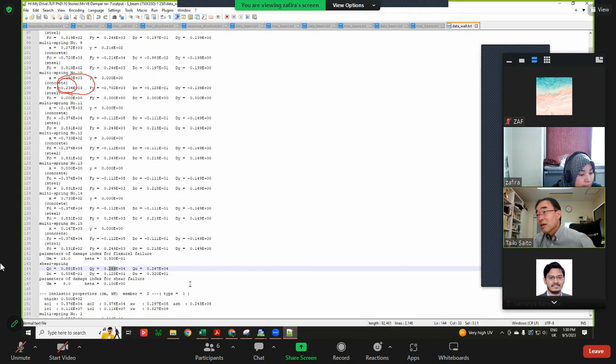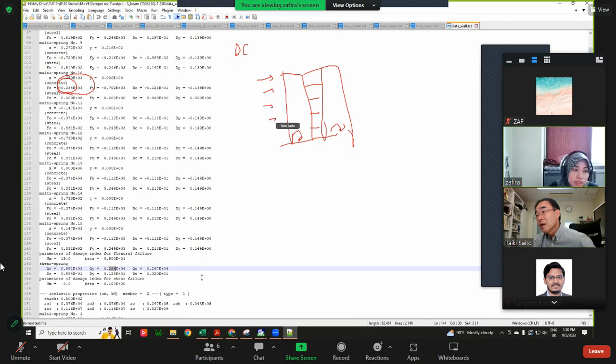Again, the degree of coupling is calculated from the moment at the bottom of the shear wall and the shear force of the coupling beam, right? Yes. But it depends on the loading condition. Yes. But last time, Sensei, we tried to change the pushover, like 1/100 or 1/250. It doesn't make much difference.